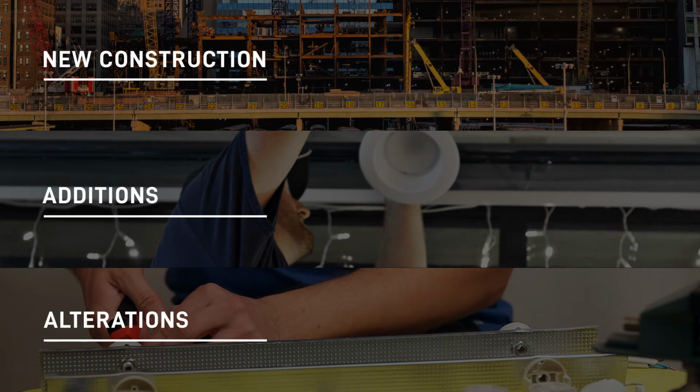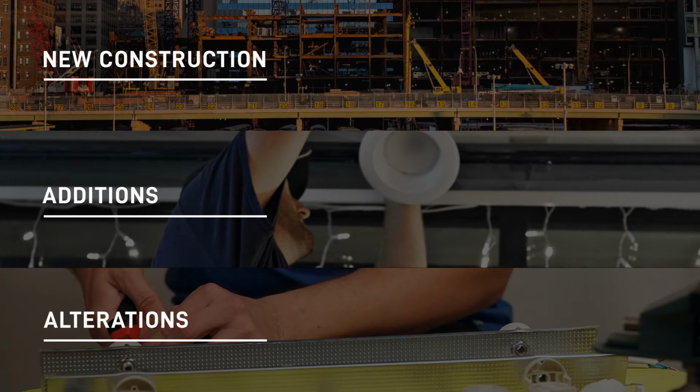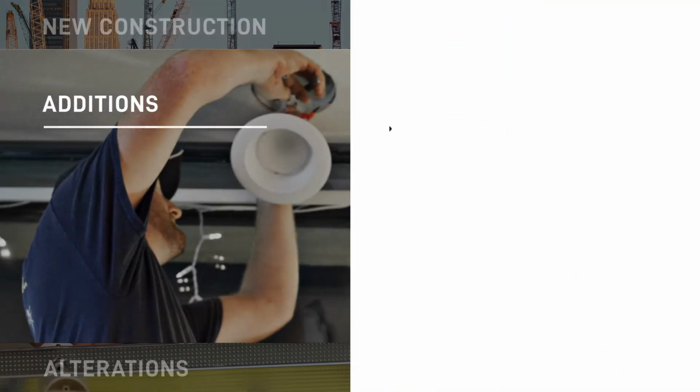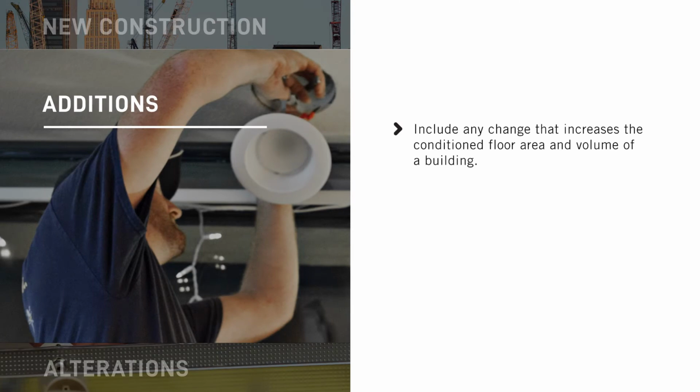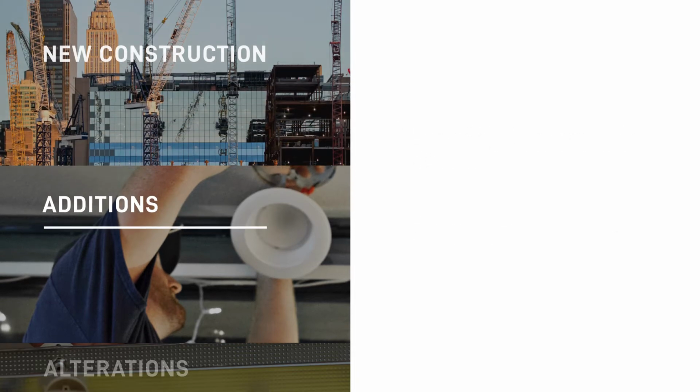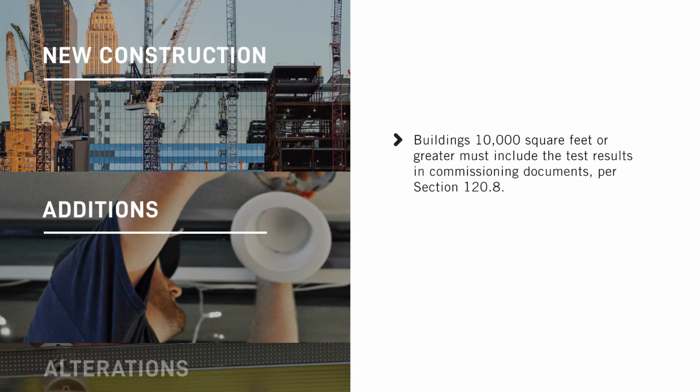Acceptance testing applies to all new construction, additions, and certain alteration projects containing these lighting control devices or daylighting envelope features. New construction is the construction of entirely new buildings. Additions include any change that increases the conditioned floor area and volume of a building. It also refers to changes that increase the illuminated area of an outdoor lighting application. For both new construction and additions, buildings 10,000 square feet or greater must include the test results in commissioning documents per Section 120.8.